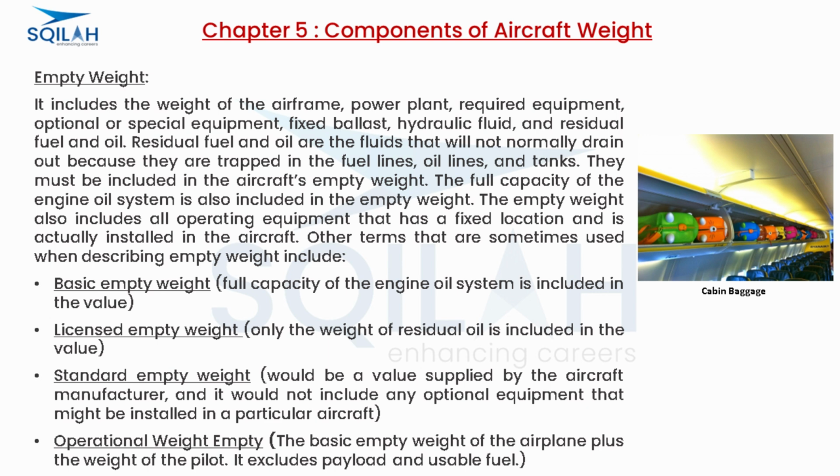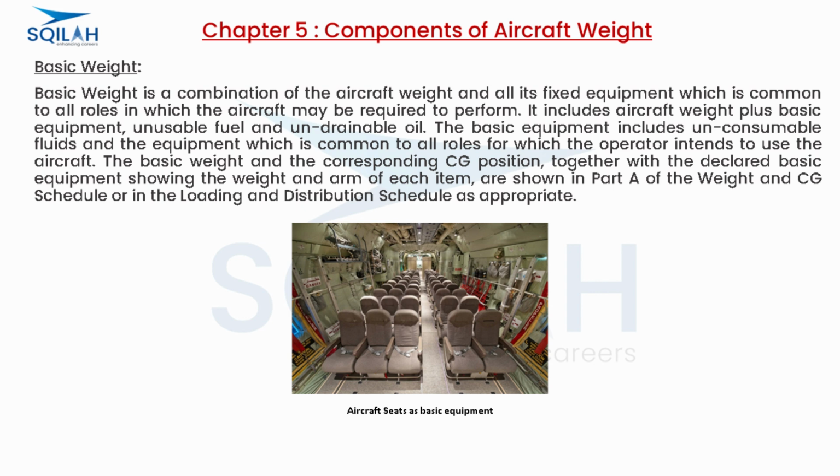Operational weight empty. The basic empty weight of the airplane plus the weight of the pilot. It excludes payload and usable fuel. Basic weight. Basic weight is a combination of the aircraft weight and all its fixed equipment, which is common to all roles in which the aircraft may be required to perform. It includes aircraft weight plus basic equipment, unusable fuel, and undrainable oil.